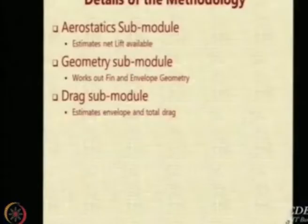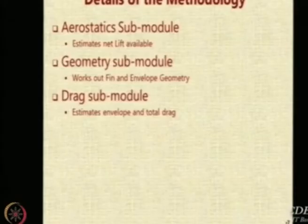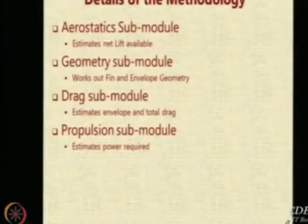Then there is a drag submodule which estimates the total drag of the airship under some operating condition. The main part of the drag of the airship, nearly half, is going to be the envelope. So envelope drag estimation, and then scaling up by some semi-empirical methods to get the drag of the entire airship. Then there is a propulsion submodule. Given the drag expected at an operating condition, it works out the power required, and given the power required for a particular engine type, it works out the horsepower or weight of the engine and the fuel consumption also.